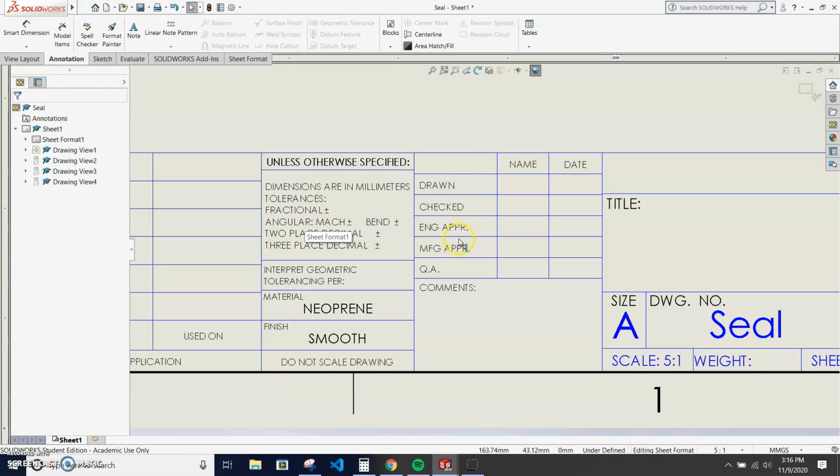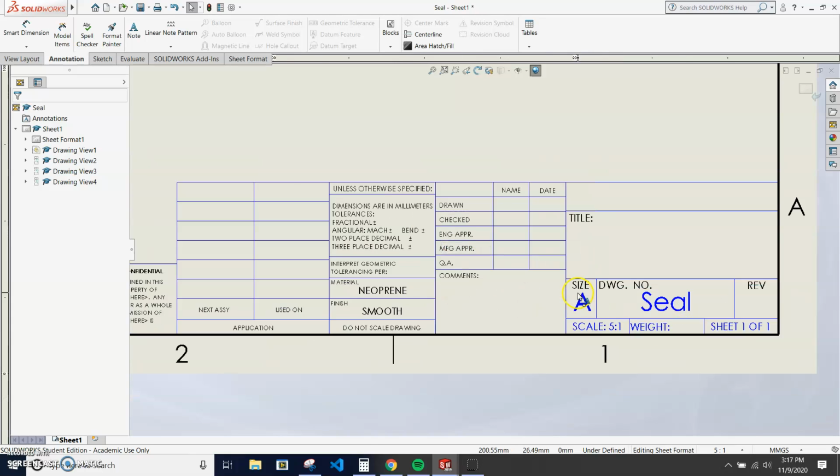This is a legal document. So if that part that we designed comes back and it is out of spec, it didn't meet the tolerances, it's on the manufacturer, right? If the part came back and it's in spec, but it doesn't fit our assembly that we've been working on, it's on us in-house, right? So there's some big money sometimes on here.